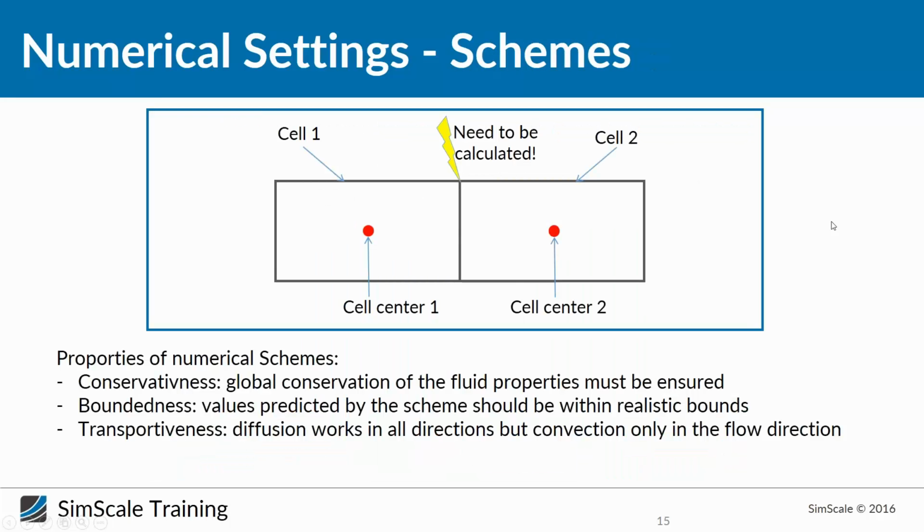Okay, and now we come to the last part. If you think about what we've talked about so far, we talked about, first of all, how we define convergence and how this result is calculated. We talked about how we calculate the result based on the different iterations, but we did not talk about another problem. If we have discrete values between the points, then in the end we need to calculate the value at the face, because otherwise we cannot run the simulation. Since we're using this discrete mesh, we have a problem because we don't know the value. We just need the value here and here. And therefore we use so-called schemes. They are in the end used to interpolate or also to calculate other things we need, like gradients, etc.